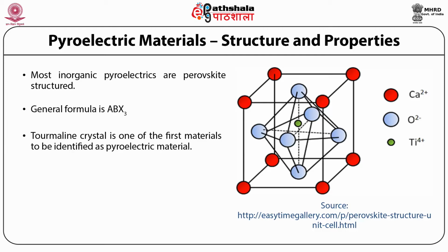The general requirements of pyroelectric materials are high pyroelectric coefficient, physical and chemical stability, low relative permittivity, low piezoelectric response, low cost, high quality and ease of processing. Pyroelectric materials can be classified in four main areas: single crystals, ceramics, polymers, and thin film materials.